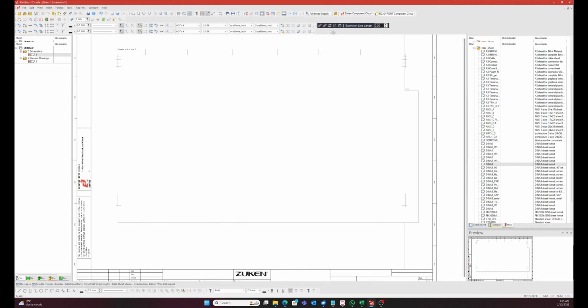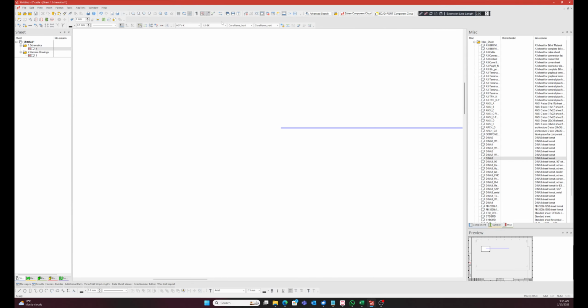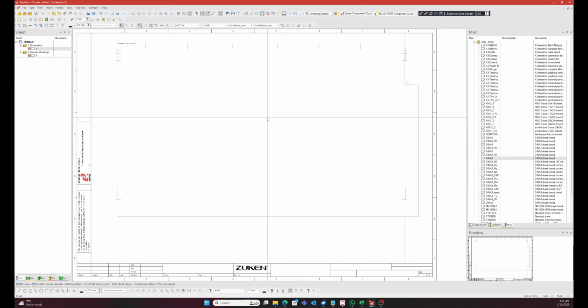And then I might even move this over here just because I've got heaps of space. The rest is pretty good. I want to put this button on by default, mark inline connection points. It just means that when I draw a connection line, the dot will appear like so. The reason why I'm switching it on now is I want some of these default settings to be ready in my template file, which is the next step I'm going to do.